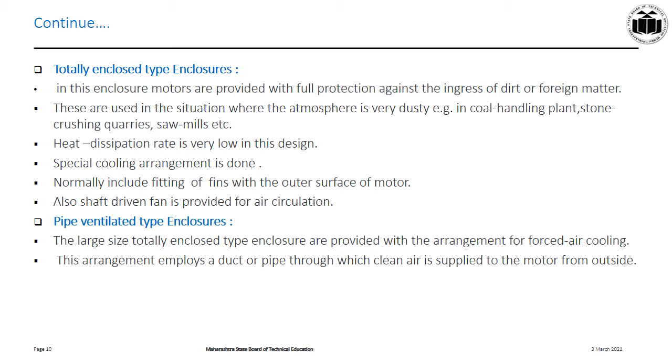Now since it is totally enclosed, the heat dissipation rate is very low in this design. Therefore, special cooling arrangement is a must. So cooling fins are provided, like those seen in a power transformer or bigger electrical devices. Normally, it will include cooling fins on the outer surface of the motor. So it will increase the cooling area and the drive will cool down very fast. Also, a shaft driven fan is provided for the air circulation at the end.